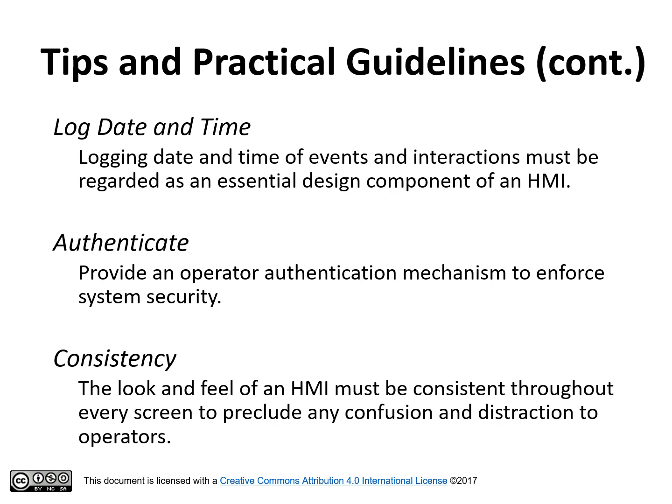Logging date and time of events and interactions must be regarded as an essential design component of an HMI. By keeping a record of events, alarms, and variables, process automation can be reviewed and improved. Furthermore, these logs provide essential information that can be used for the continuous improvement of the HMI.